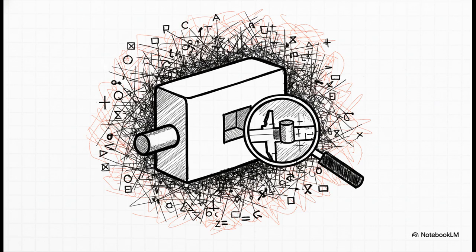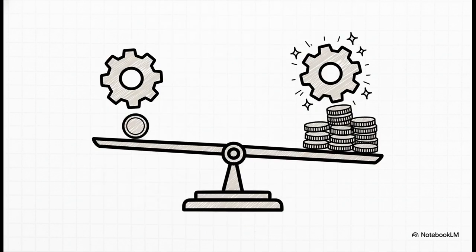This is where a drawing demands a level of perfection that is just completely unnecessary for the part to do its job. Here's the thing you have to remember. Making a part 10 times more precise than it needs to be doesn't actually make it better. It just makes it way, way more expensive. You're putting this huge burden on the people making and inspecting the part, driving the cost through the roof for absolutely zero functional benefit.